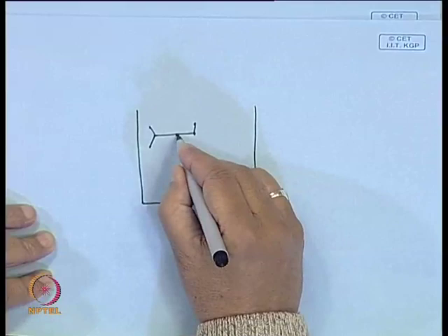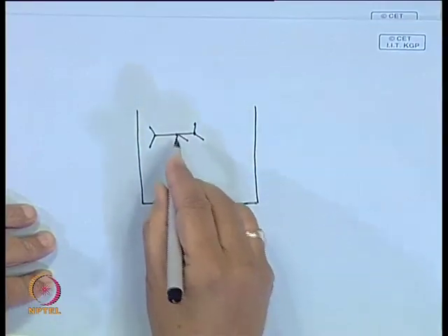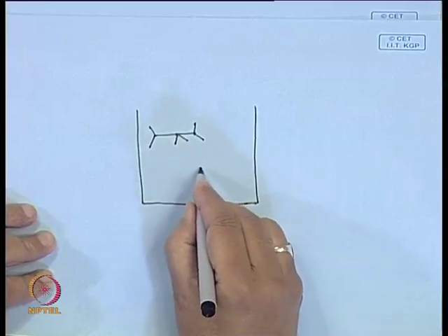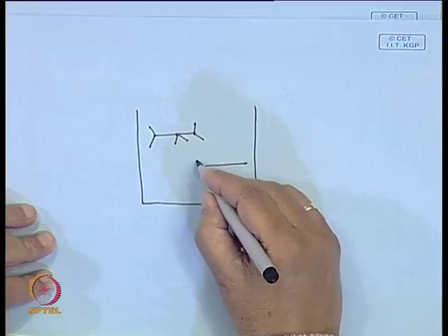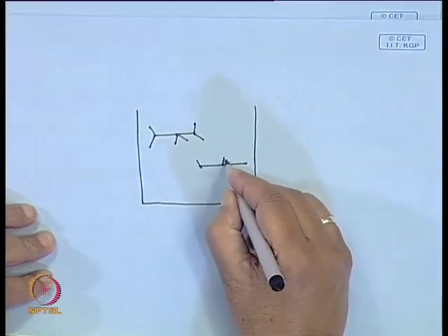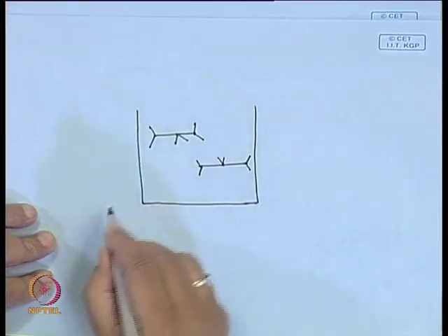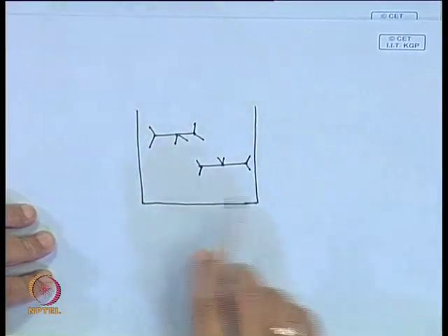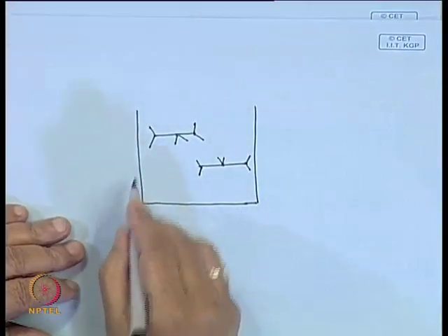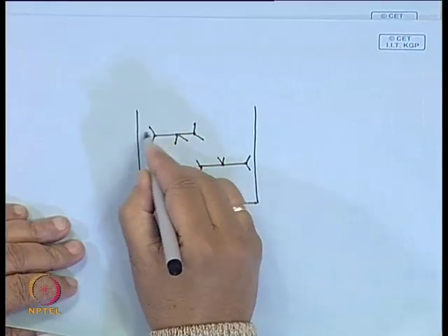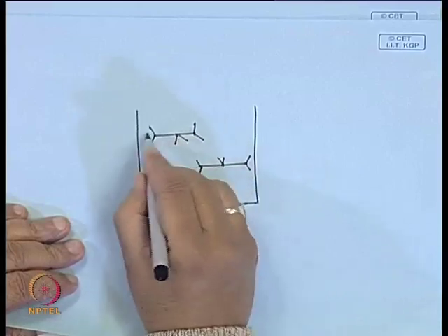So, this is a two phase region, and similarly the eutectic will also be at a fixed temperature, somewhere you draw this, and then you try and join. Then you follow certain rules like the two phase regions should be separated by single phase regions.